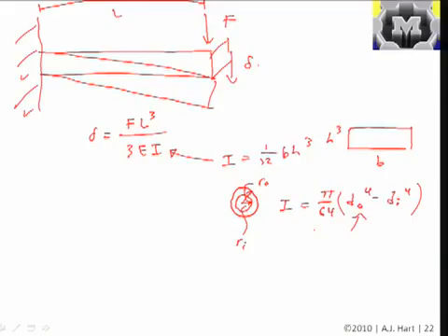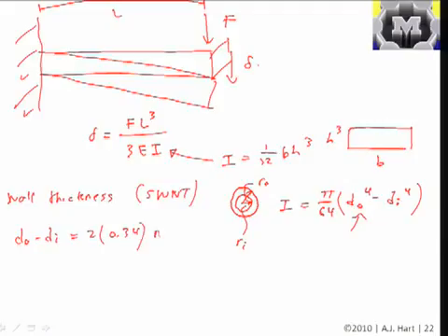So then the question is, if we have a nanotube, a single layer of atoms, what do we define as the outer and the inner diameter? Or basically, what is our wall thickness? It turns out that going through a treatment that's beyond the scope of what we want to do, we can basically assign for most nanotubes a wall thickness for a single wall nanotube to be twice 0.34 nanometers, where 0.34 nanometers is the interlayer spacing of graphite.